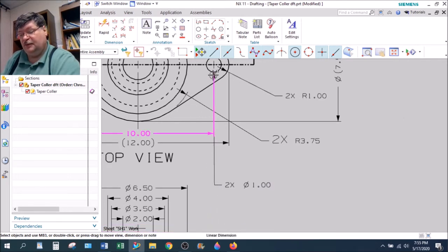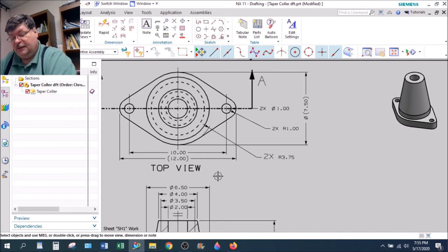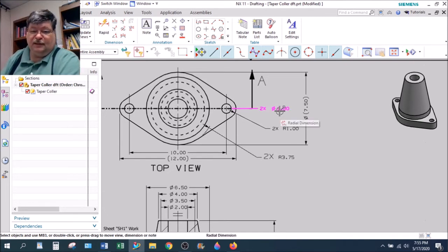That leader line just sort of disappears, and you might find the arrowhead, but the leader line's hard to see. Horizontal, same way, it kind of hides in drawings, because in drawings, oftentimes there are a lot of vertical and horizontal lines to hide behind. So don't do that. Always bring it out at least like 15 degrees from horizontal or vertical.